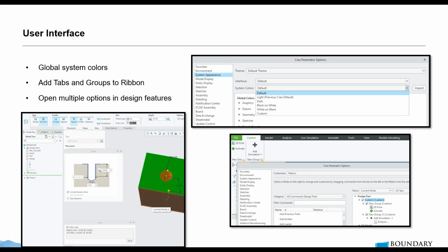The important bit is to use the defaults, and then from there, chop and change it. Even if you go from one version to another version, use the defaults, and then you can change some of the line edges or things like that. Don't copy and paste the system colors file all the time. You're going to run into issues when you get into drawings and things like that, because PTC chop and change them quite often.